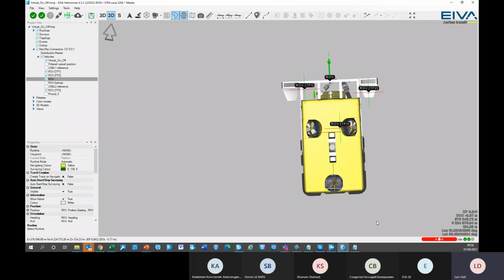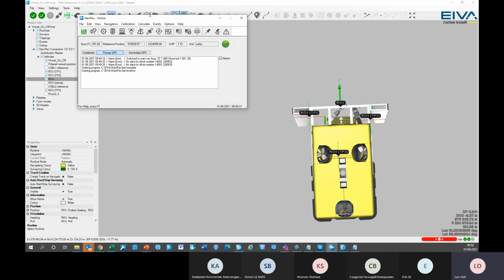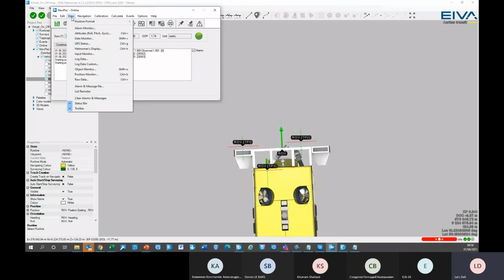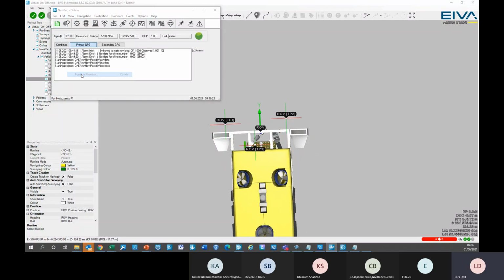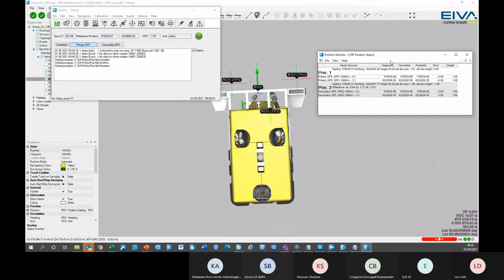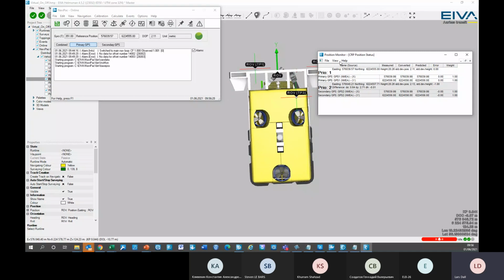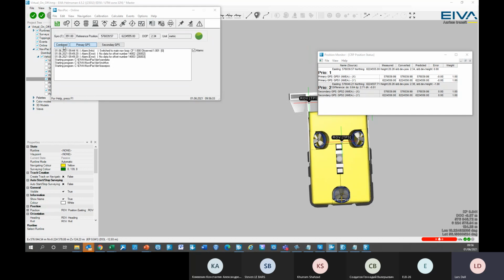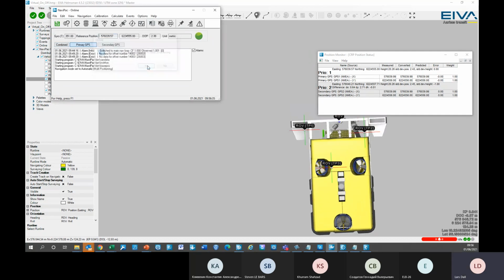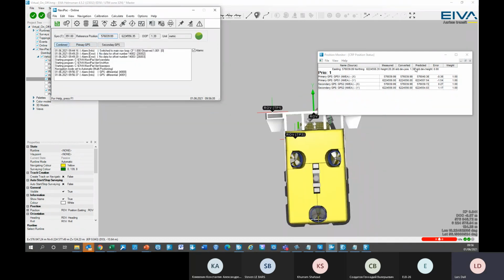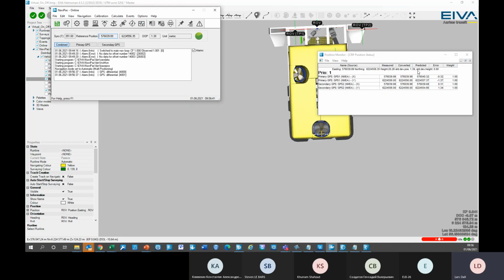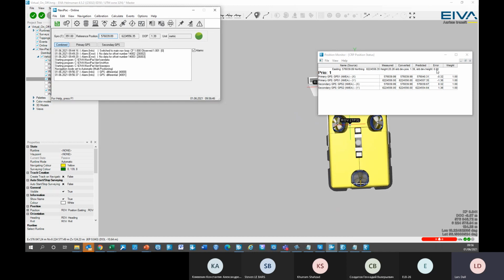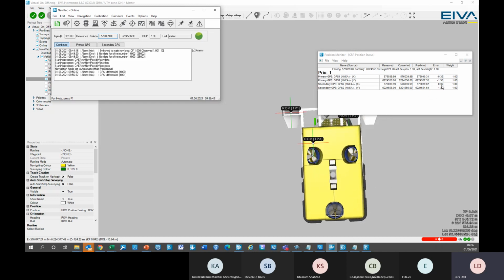Let's have a look at how we can see the quality of these. Remember yesterday, we were using the position monitor to determine the quality of what we were receiving from the GPS instruments in a combined solution. I didn't mention that yesterday, but you can actually see the standard deviation of the position here. And of course, that's based on the residuals that we have.